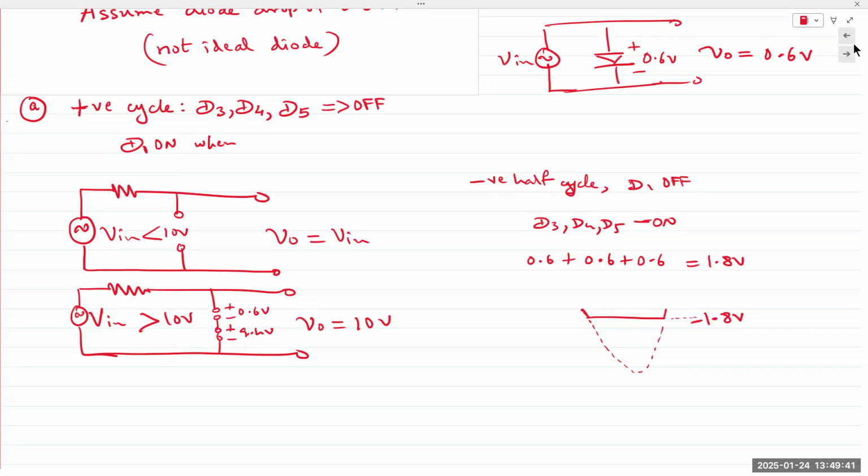If you're using regular silicon diodes, we can change the value of the battery and change the clipping levels. With the Zener diode, it's a fixed 9.4 volt Zener. We are fixed at 9.4 volts. We cannot easily change it without inserting a battery, and so we can't change the clipping level.